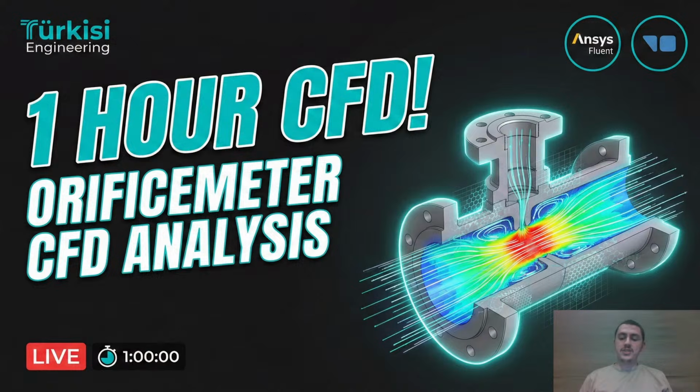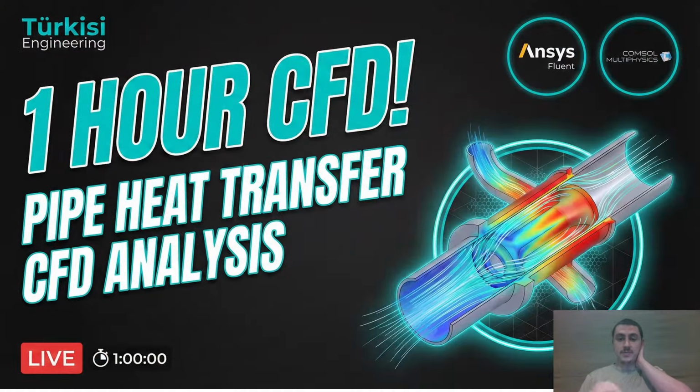So the upcoming lecture will be on the orifice meter. We will simulate orifice meters similar to Venturi, but you see a sudden decrease here. There is no transition. A sudden decrease, and you have a lot of vortices. So this is the orifice meter. More energy is lost, but it's also a way to evaluate by the pressure drop after the orifice meter. You can also measure the flow rate. So this will be our second example, inshallah.